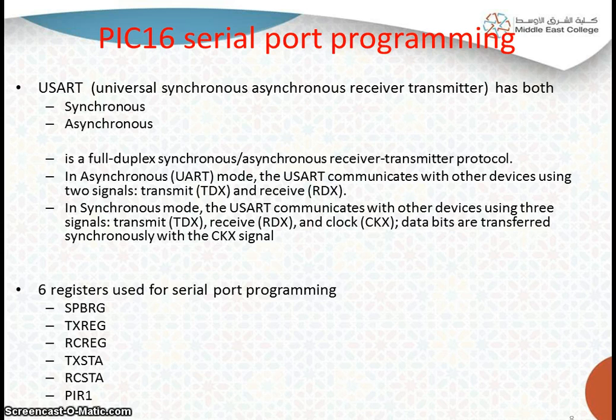and in the case of asynchronous mode of the PIC16F UART, the two devices will be using two signals, transmit and receive, because the transmitter and receiver are running at their own speed.